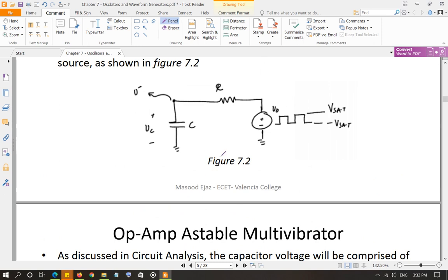Basically, you let the voltage run for the longest time, and the capacitor will be fully charged eventually and become open circuit, and whatever voltage appears across the capacitor at that time is considered the steady state voltage. So if this output is at Vset and we let this circuit run for the longest time, of course the capacitor will be completely charged and holding the voltage Vset.